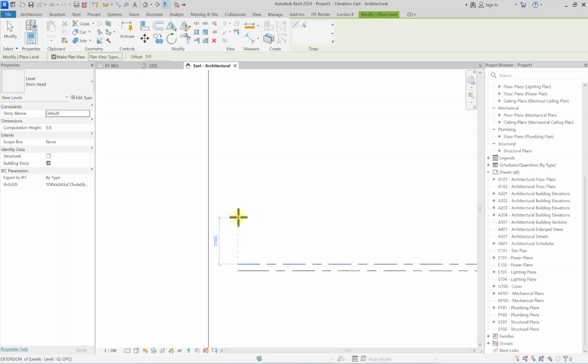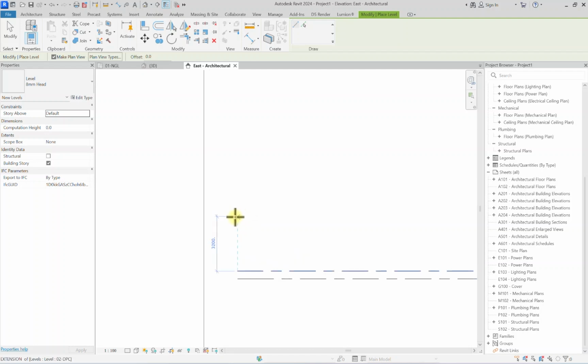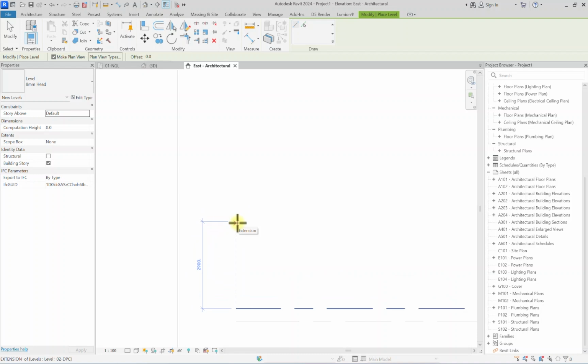or deck. So this deck now, once you are placing levels, another thing to consider is the slabs. In Revit, if you create a level and you go to that floor plan level and draw a floor slab on it, the thickness of that floor slab is going to offset downwards. By the thickness offsetting downwards, it's going to chop into the space you allocated to that level. So it's always good to consider the thickness of the floor while creating space.